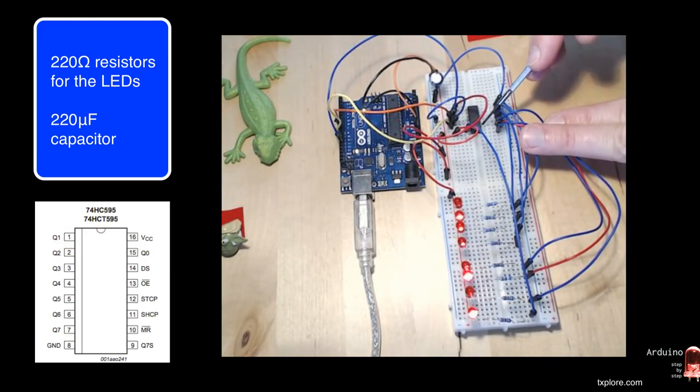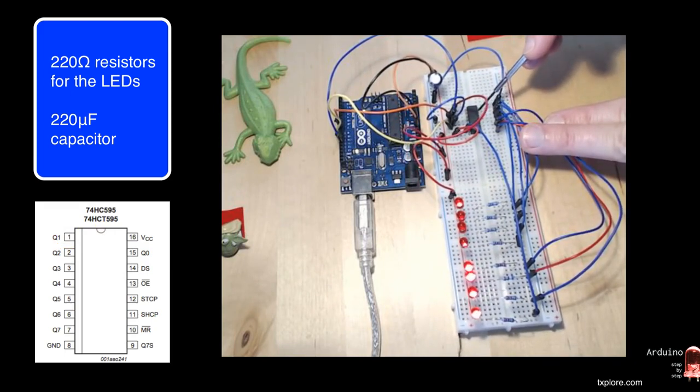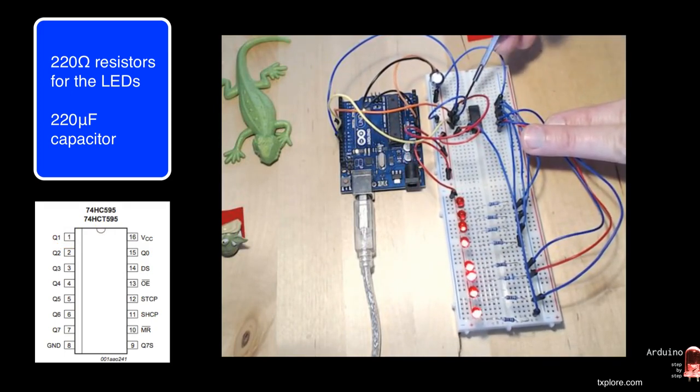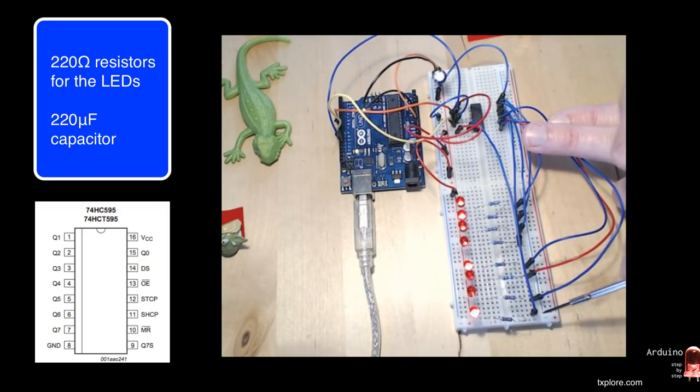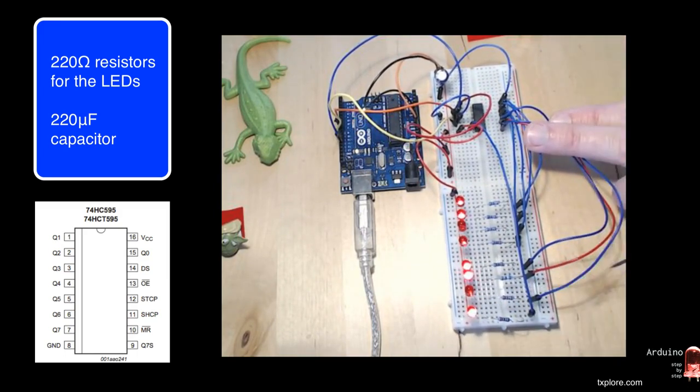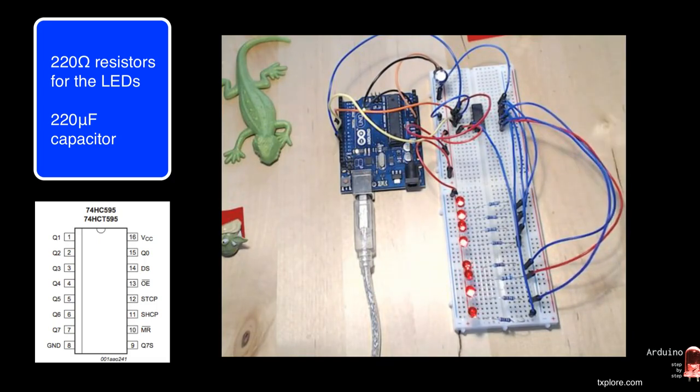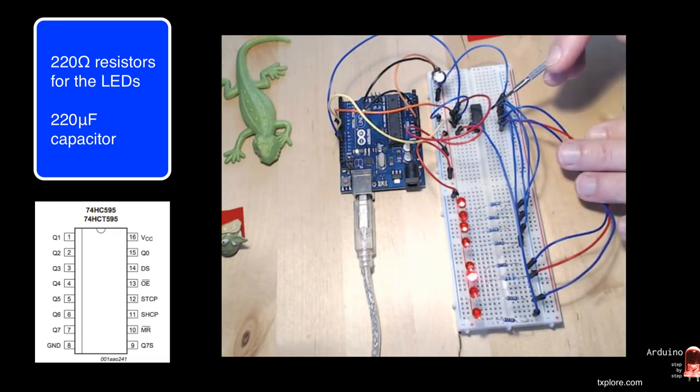So this is number 1, 2, 3, 4, 5, 6, 7, 8, and switching to the other side, 9, 10, all the way to 16. So I'm looking for pin 15 and connecting that to whichever LED I'd like to correspond to data output 0. Then, as per the schematic on the data sheet, data output number 1 is on pin number 1.